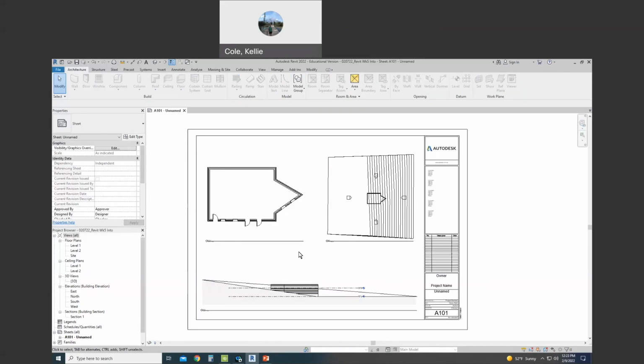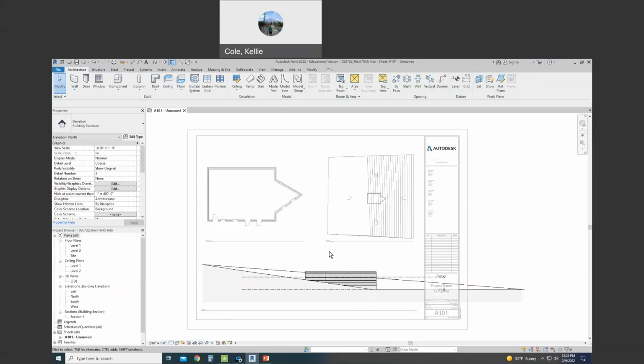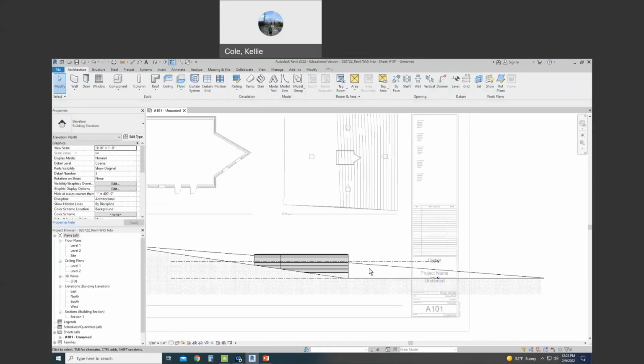So we'll learn about crop regions then. So let's say that my scale is just too big. I'll make it 3/16. If I double click in the view, we can align the window frame to show less of the drawing. Just a little hard to find. So in the properties menu, scroll down until you see the area of extents.